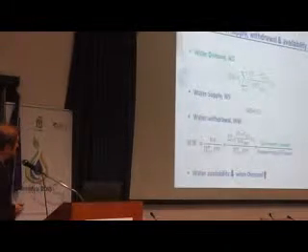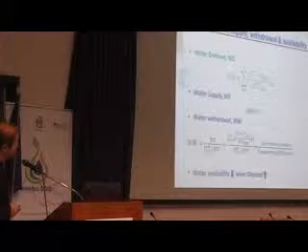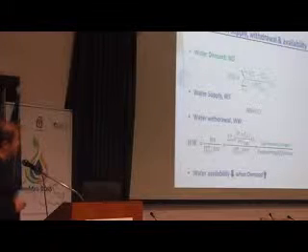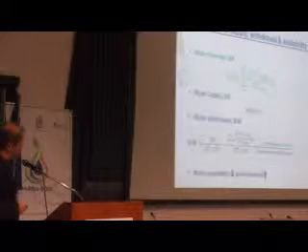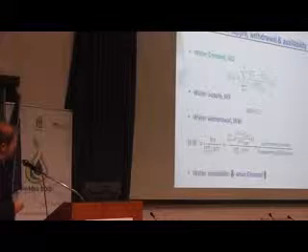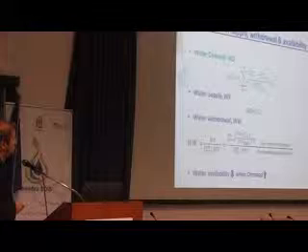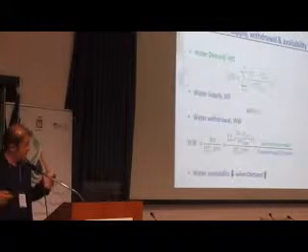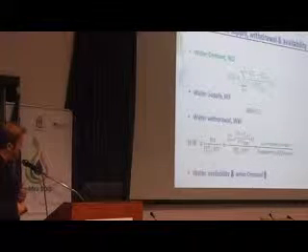So inside this concept, if we understand that water demand is something that we can estimate as the difference between crop evapotranspiration and effective precipitation, divided by efficiency of water application, and on the other side, we can try to satisfy it through the supply, we are going to understand that our water withdrawal, whatever the resource is, is something that is the ratio between agronomic demand